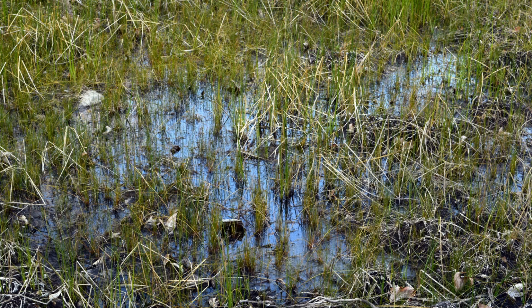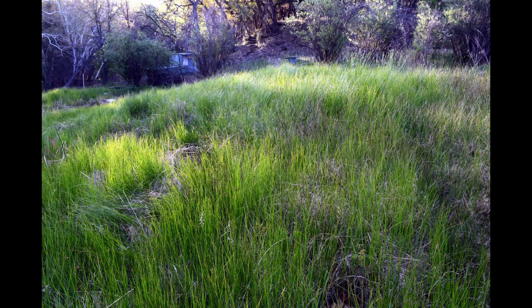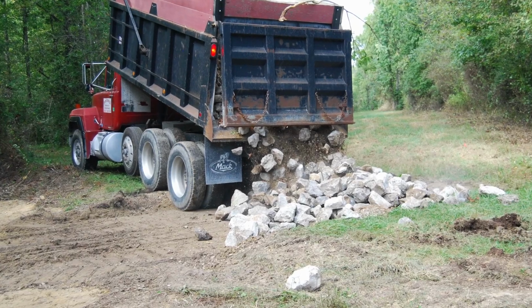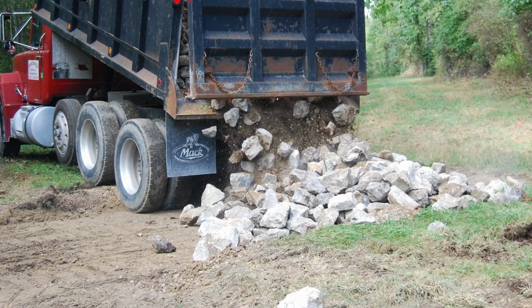This is done by building a spillway at least 12 feet wide that flows down a slope of less than 1%. The spillway may not need to be armored with rock if it's built to be wide with a sheet flow of water over a slope of less than 1%. It's very important to use rocks to armor the spillway to prevent erosion if the spillway is built on a slope steeper than 1%. The rock you use to armor a spillway should be fractured and angular, not round.